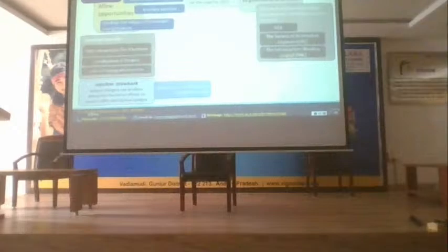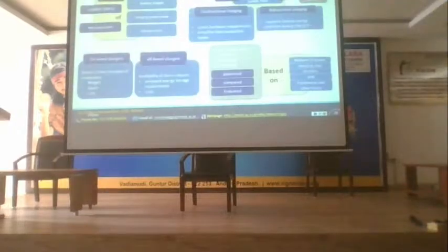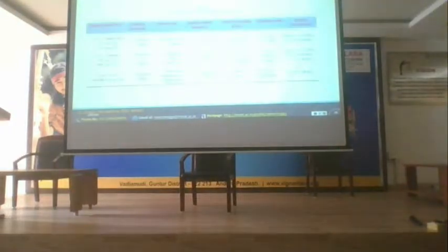So we need to take care how to handle that, and also we need to take care of unity power factor operation while charging the batteries. Those are things you need to take care of when you are making your battery and its associated charger.